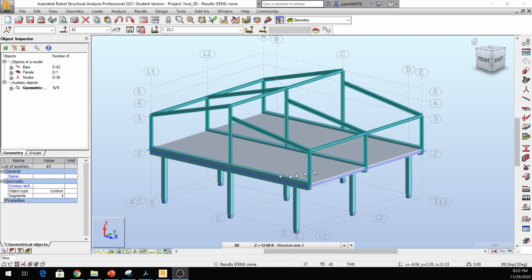We can see there is some issue here. The concrete slab should be on top of the reinforced concrete beam, but also you can see the neutral axis of the concrete slab and the concrete beam are on the same level. Let's take care of this.